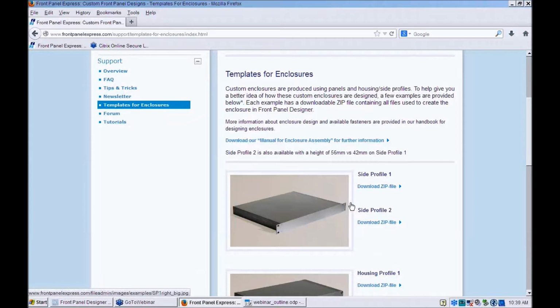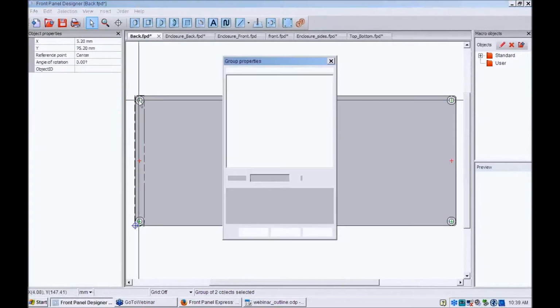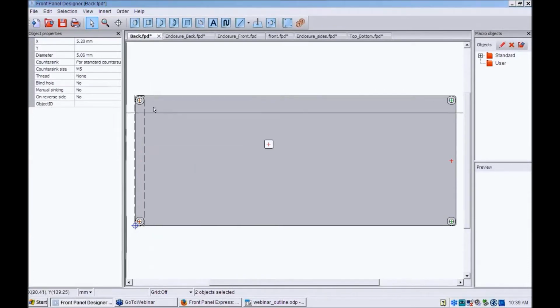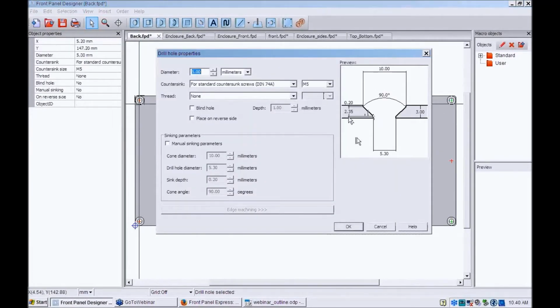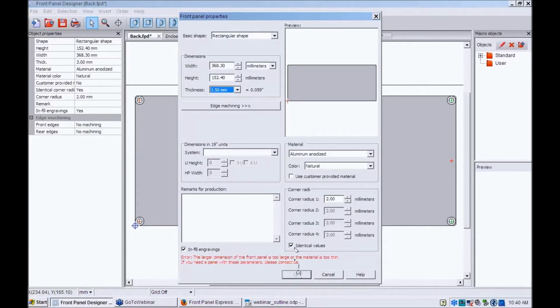This would also require a thicker front panel. In a lot of cases, it would at least need to be 2.5 millimeters in thickness. Now, if you use a 1.5 material thickness for your front panel, you would have to select a drill hole, just a through hole for your panel to eliminate the profile of the cavities. For example, if we set our properties to 1.5, which our panel's too large.